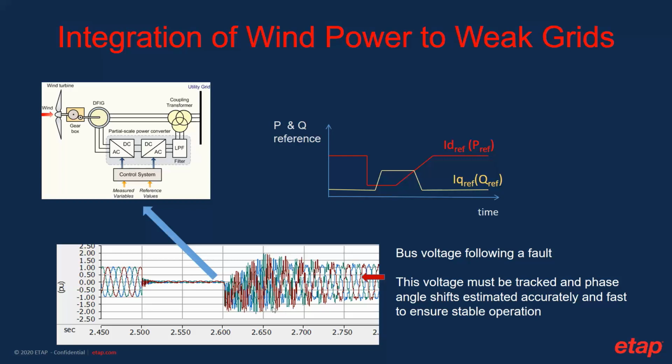In order for that, it is very, very critical that the so-called phase lock loop of the control system of the wind farm accurately captures the voltage angle of the fundamental frequency component of this transient. This is the most critical measurement that the wind farm controls need to do their job properly or to successfully ride through the fault.